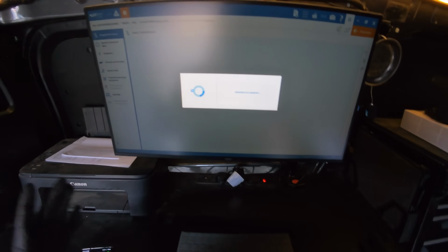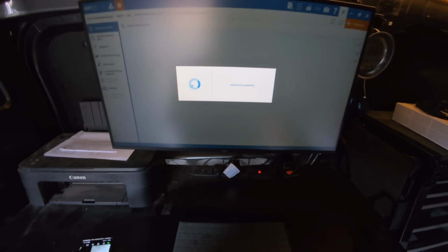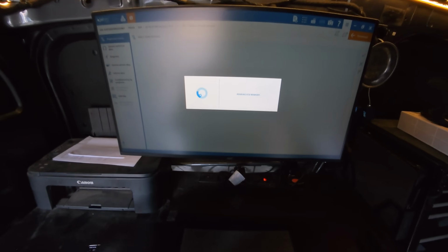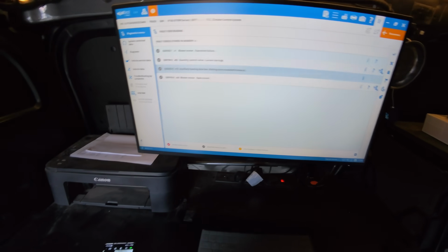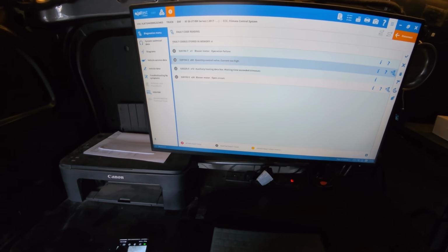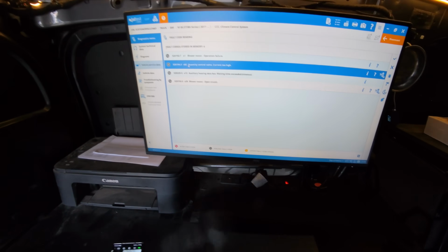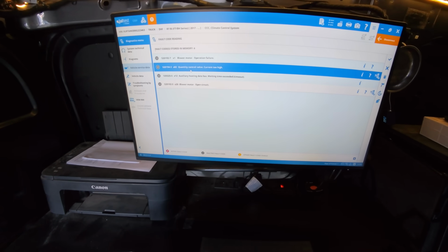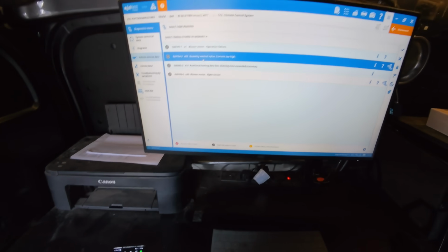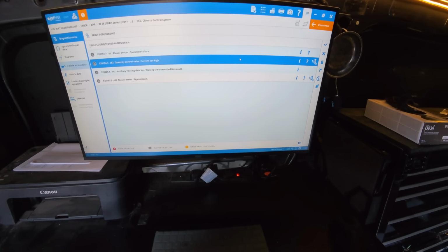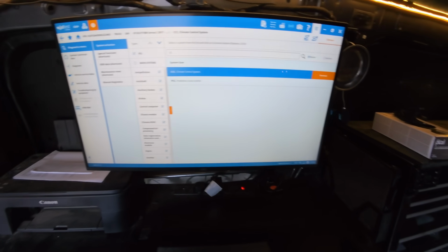So the reason I think the customer is sometimes getting heat, or is not getting any heat at all, is nothing to do with the air mix flap actuator, because we'd have faults for the actuator. All we've got is the quantity control valve current too high. So I think the 3-2 valve's getting stuck, and that's isolating his small circuit from the engine coolant. That's what I think he should change. So that's our cabin climate control issue.